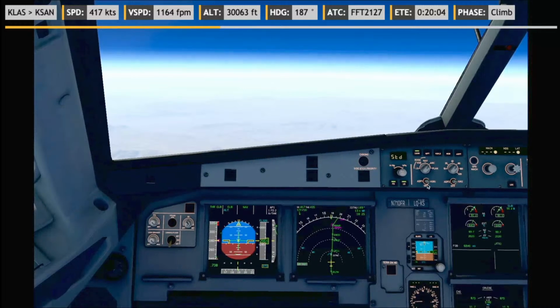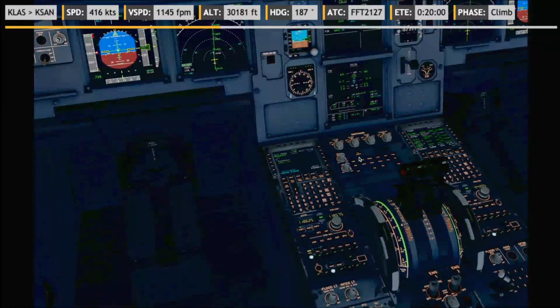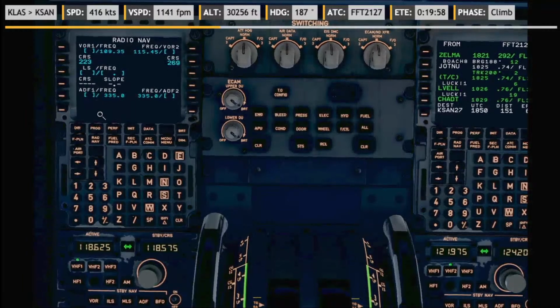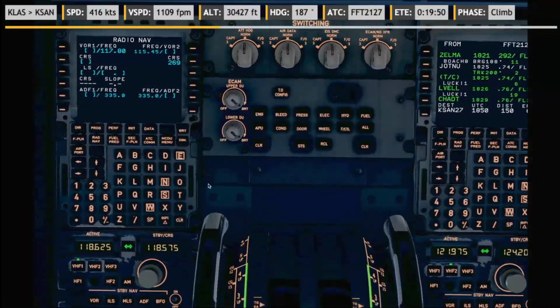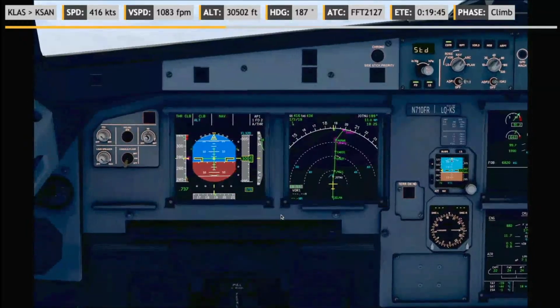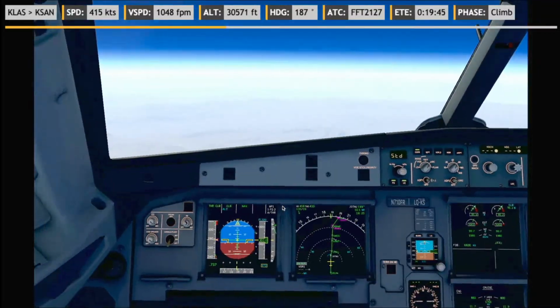Might be a good idea. Let's get Mission Bay in our VOR 1. So we'll go in here. RadNav VOR 1. 117.8 is Mission Bay. 7.8. Selected. See if we get anything. Nothing yet. It's fine. We're still quite a while out. Alright, that's set up.